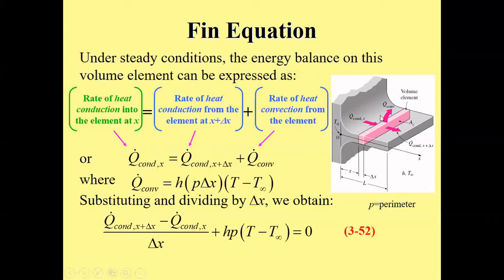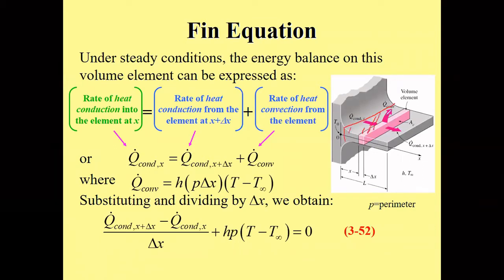So you see the surface of this fin, around this area. We can take this as the surface: the top surface, the bottom, and also the two sides here, and also the tip here. But usually the tip is so small that if you don't include it, it's okay. It can be negligible compared to the surface on the top and at the bottom.